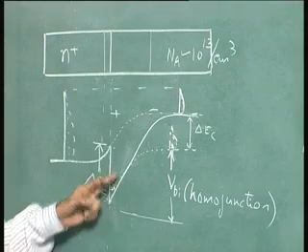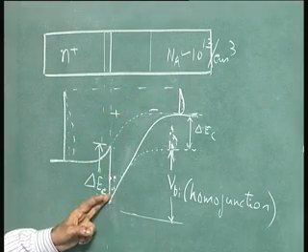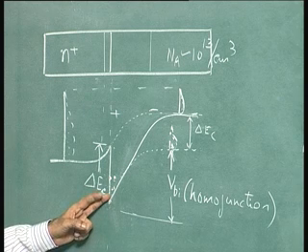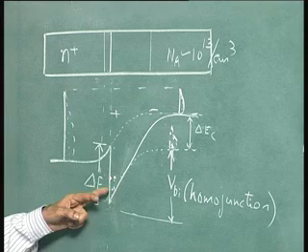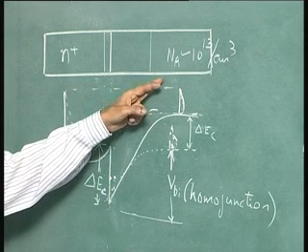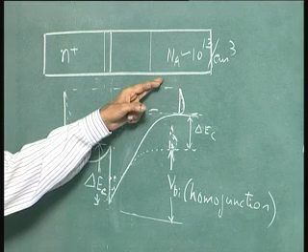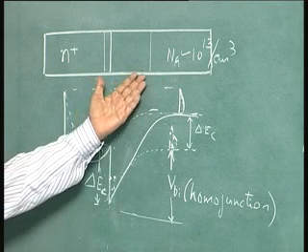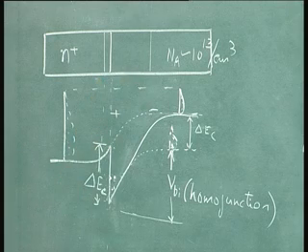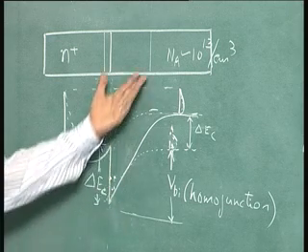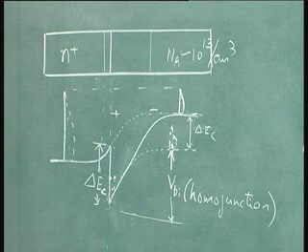electrons are in a region where the dopants are low. Okay. So, ionized impurity scattering is reduced. How much it is reduced depends upon how low the doping concentration is. The other thing is how much of the other impurities there are. When you grow the material, other impurity concentration also must be reduced. So, over the years, they could improve the mobility of electrons here by getting purer and purer layers grown, by epitaxial growth, MOCVD and MBE techniques.